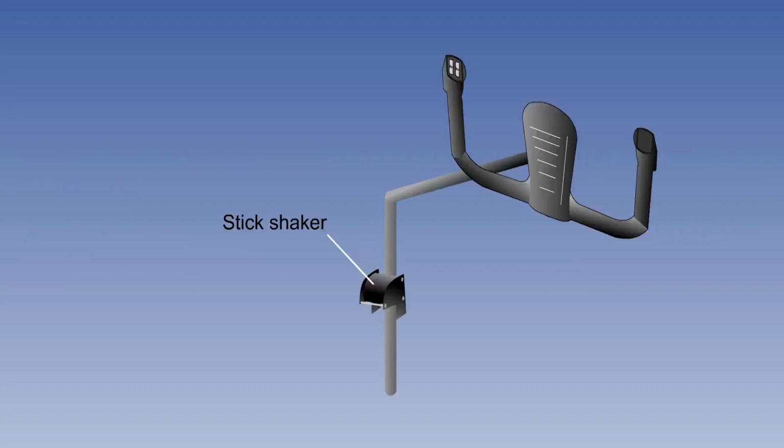The stick shaker is intended to represent the aircraft's natural buffet by replacing it with a tactile warning. The noisemaker is added in parallel to ensure that the warning is noticed if the pilot's hands are not on the controls, for example, if the autopilot is engaged. The device consists of a pair of electric motors, one on each control column, rotating an eccentric weight to generate vibration.